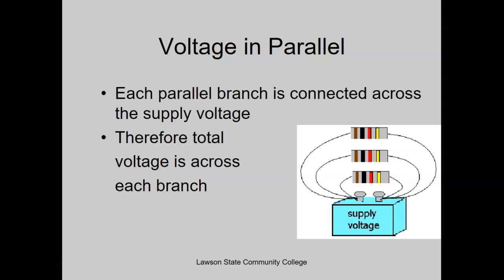Why are every light that you come across 120 volts? Because they're all parallel, right? They all connect back to source. They're all across that same positive and negative run. Okay? So you literally have full voltage across every light. You have full voltage in every plug.